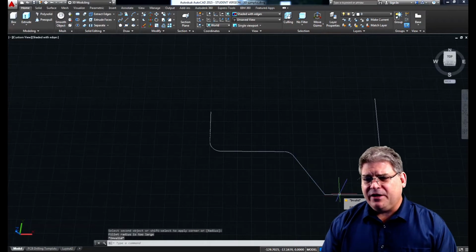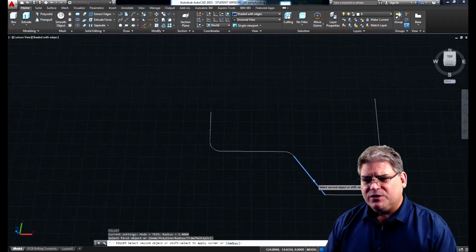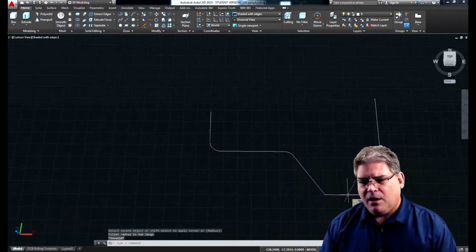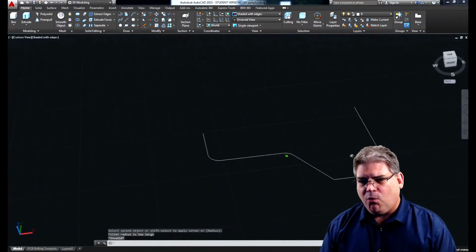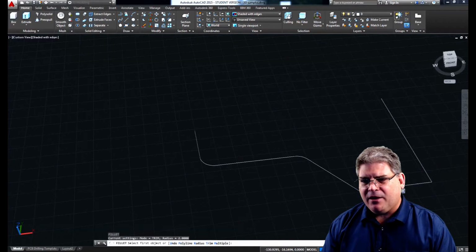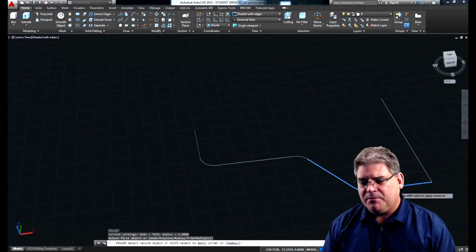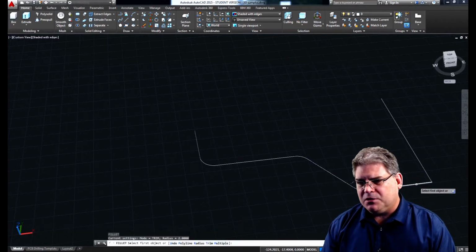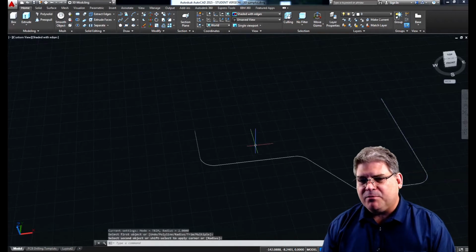One thing that is important when we use the sweep command is that we can't, well, you can, but you don't really want sharp corners. So think about your bend angles if you're creating geometry for, say, a wire that's being bent. There's a minimum bend radius.